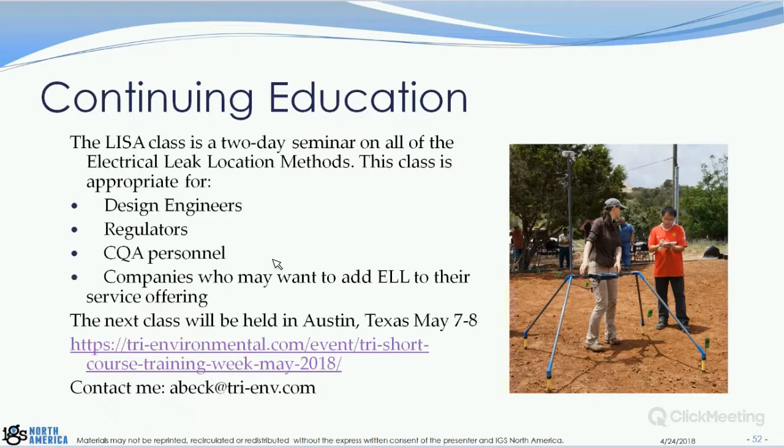Can you comment on typical costs? Yes, the typical costs really depend on the method. I can tell you specifically about dipole testing, especially if you can count on a 10 by 10 grid. As you can imagine, if it takes 1 day on a 10 by 10, it takes 9 days if I have to go to 1 meter by 1 meter. That's a very different cost. But the typical cost for the dipole method, as long as the site is prepared properly and you don't have issues on that front, is very approximately $1,000 an acre for a medium-sized site. A 10-acre site will probably be somewhere around $1,000 an acre.